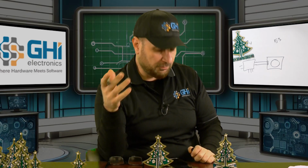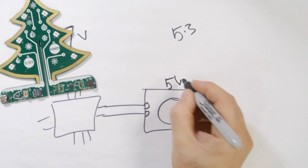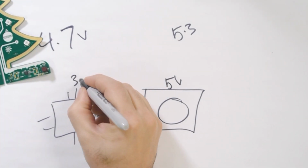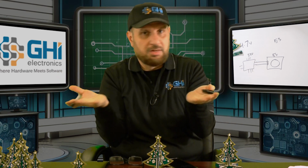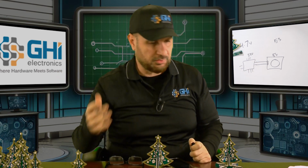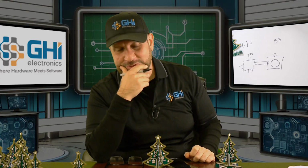But I wanted to verify that because the LED is running off 5 volts and the micro is running off 3.3 volts. So we have 2 different voltage levels, but in most cases everything should work at 3.3 volts, even if the LED is running at 5. Checking the data sheet, there is no mention whatsoever of the expected voltage levels.